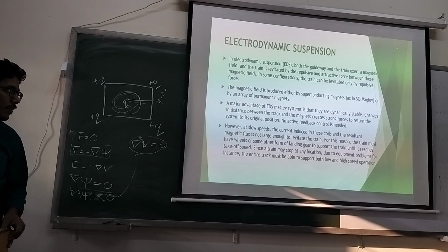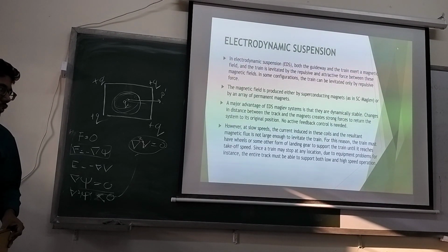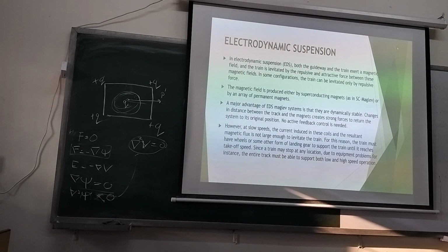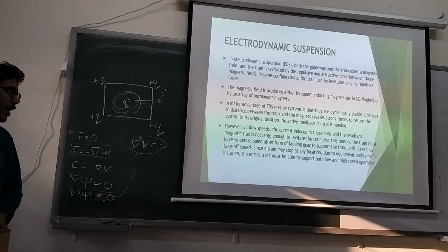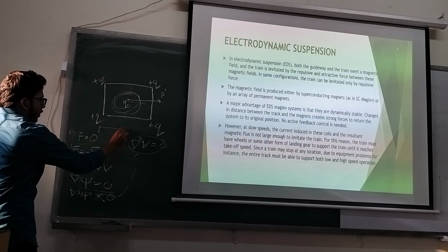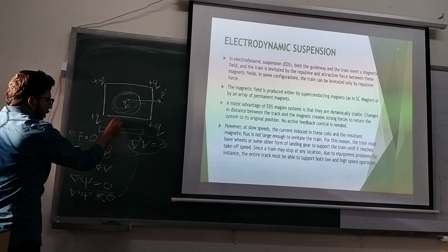A linear motor is effectively an AC induction motor in which the stator and the rotor are cut in half and laid out like a track. The stator usually has copper windings, right? It has a three-phase power supply, which produces the effect of a linear magnetic field. Essentially, the rotor, which is also known as the secondary, glides over the stator, which is the primary.